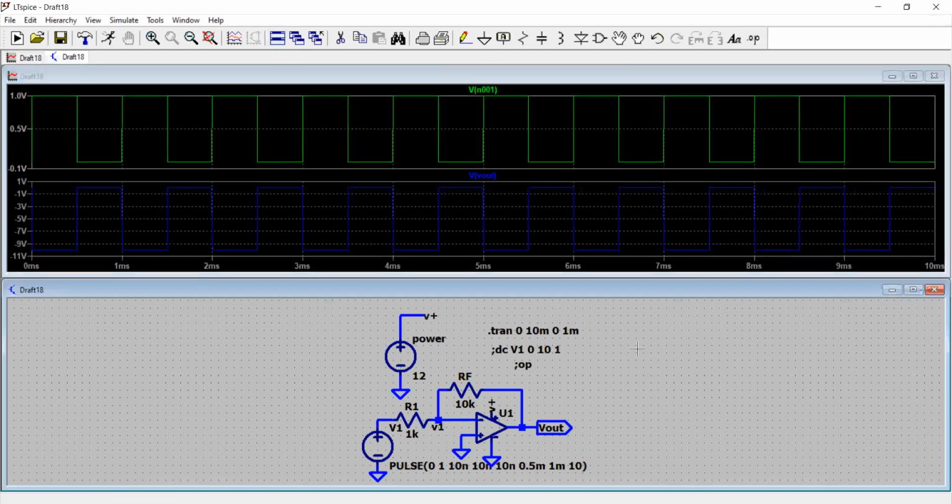How about running the frequency response? Now I will show you how to plot the Bode response. Bode response is a plot that gives you gain versus frequency and phase versus frequency. So you can express your gain magnitude or take the decibel, dB values of it.